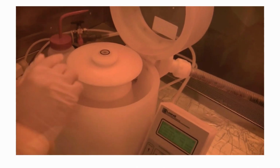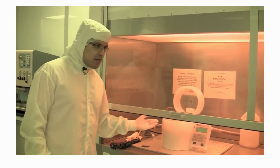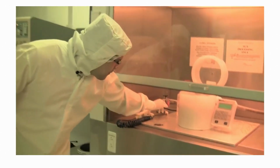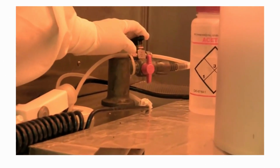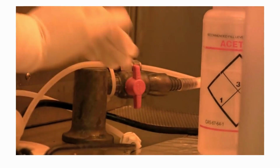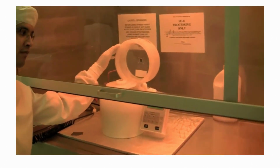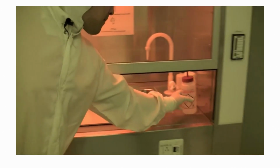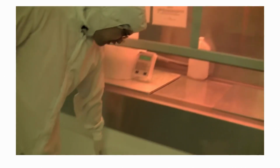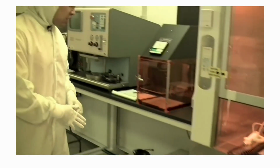But if we all take these steps to clean the inside and clean the surroundings, we can prevent this from happening and keep the tool up longer. Alright, so once the spinner has been cleaned thoroughly, you want to make sure you close these 2 valves over here. Remember the rule, if it's perpendicular, it's closed. If it's parallel, it's open. Think of it like a flow, and see how they're kind of crossing the flow? It helps you remember. You also want to close this, and put this back on the right side. You want to make sure these cabinets are closed, if you took out Photoresist, and then lastly, you want to log out.